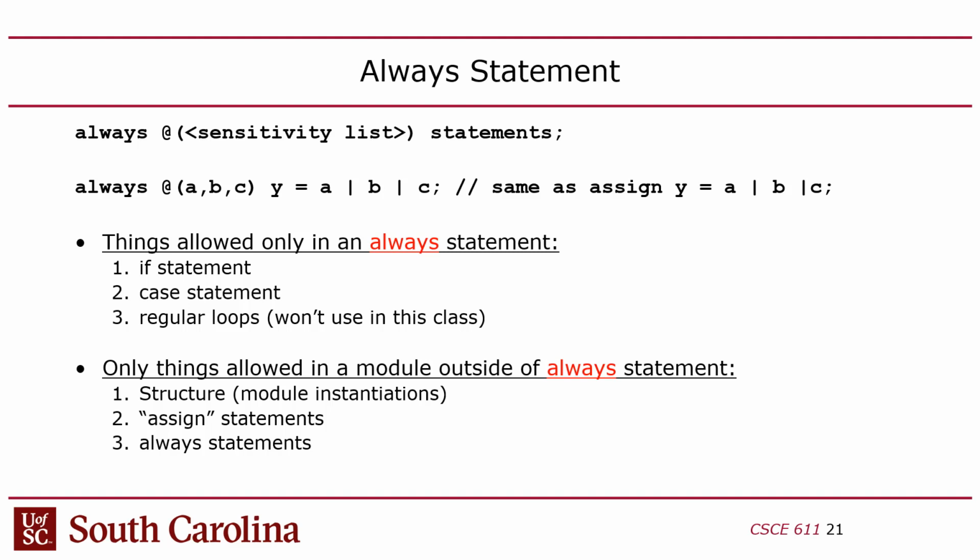Like with SPI, there is a phase where you're reading the header packet, right? The header, the first exchange, right? The address and the flags, right? That's a state. Well, there's a state where the bus is idle, right? So if the bus is idle, you're just sitting there waiting for the slave select to go low. Once that happens, then you have to go into a state where you're reading the header. Then you have to count eight cycles, right? And that 8 cycles will then cause you to go to another state where you're reading the data payload, right? So you need to have the ability to use an always statement that uses the clock to create a sequential